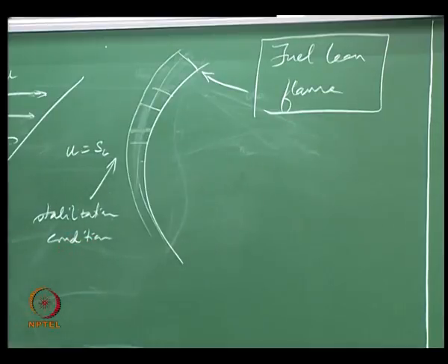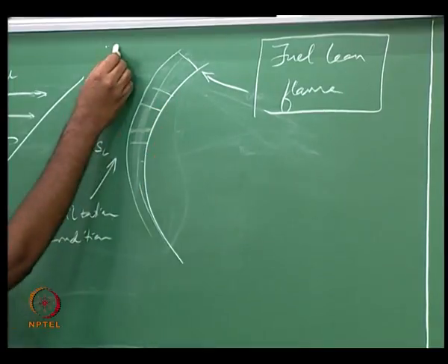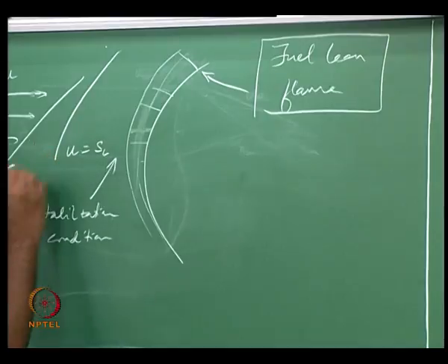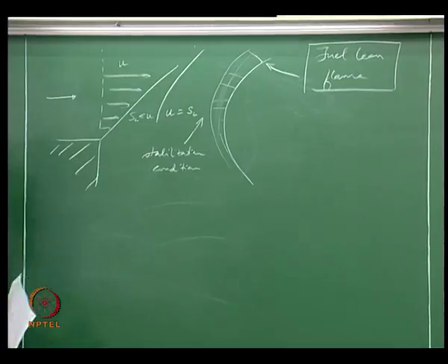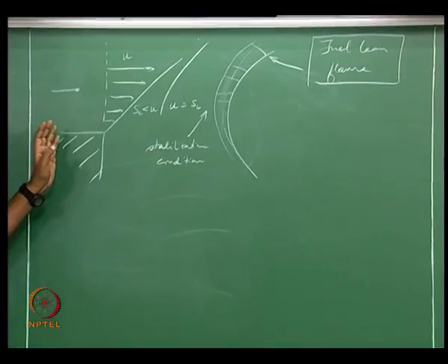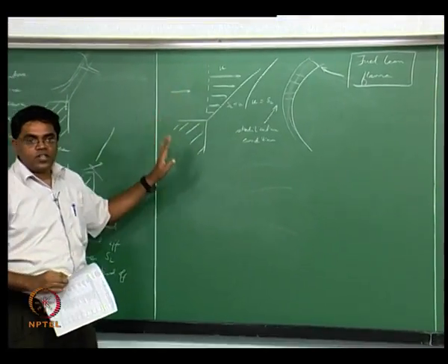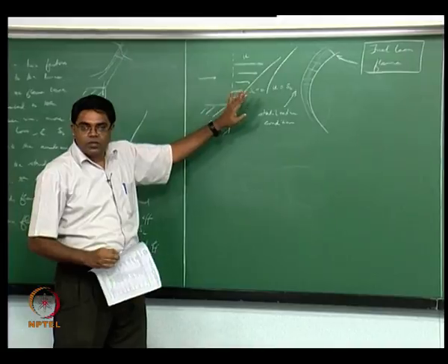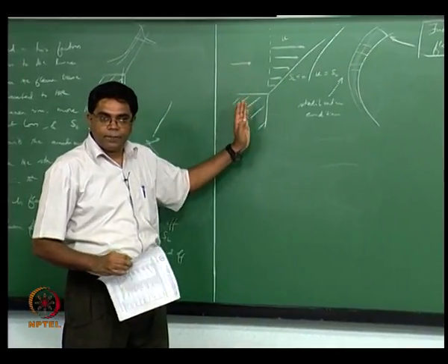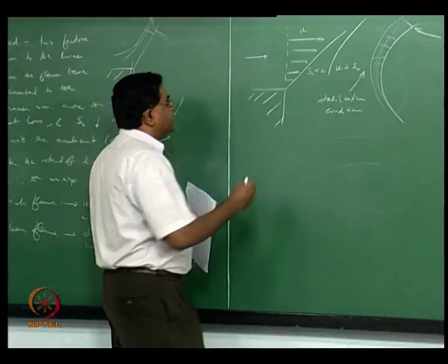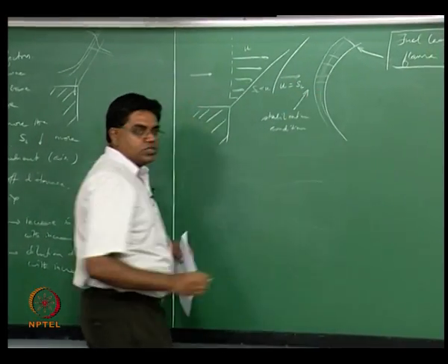Right. Now what happens when you try to have a flame that is perturbed inward, it now gets closer to the burner, right. So its SL actually becomes less than U because of a greater heat loss effect, alright, but the mixing is not much, so it is not trying to decrease the SL a lot, but the heat loss is actually trying to decrease the SL, and therefore the flame gets pushed backwards to this point.